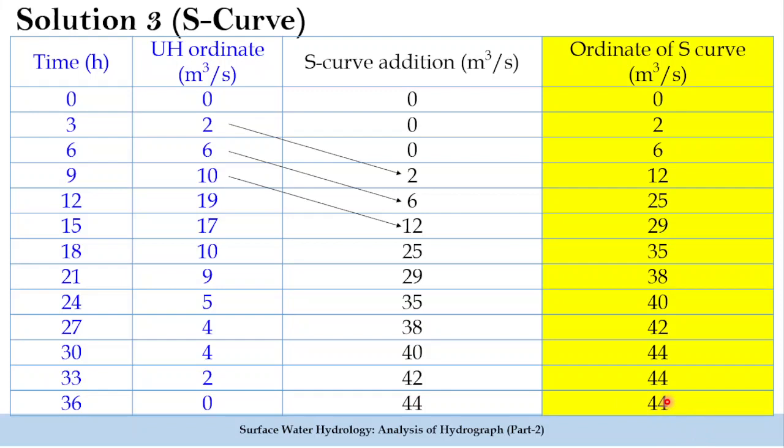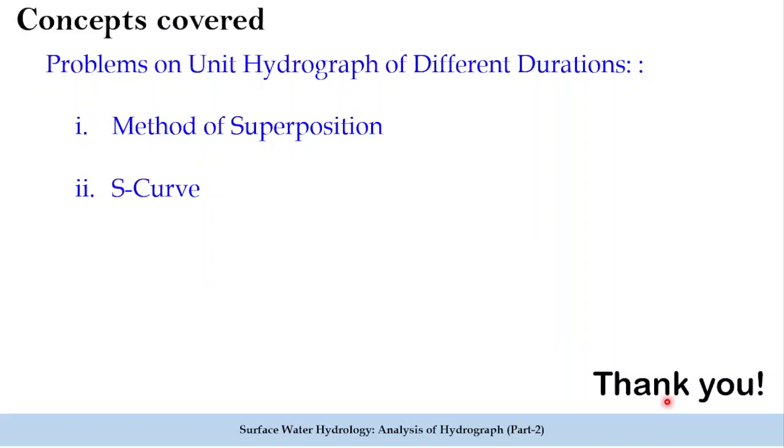I hope you were able to understand how the S-curve is constructed by using the concept of S-curve addition. So in this lecture, we focused on two methods, the method of superposition and S-curve construction for unit hydrograph. I hope you were able to understand both of these problems.